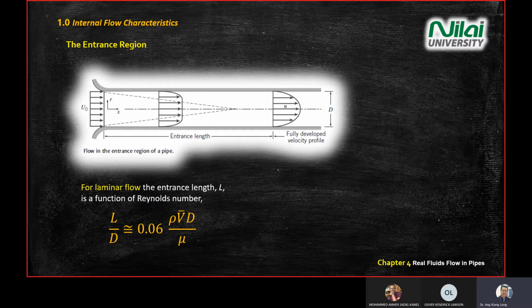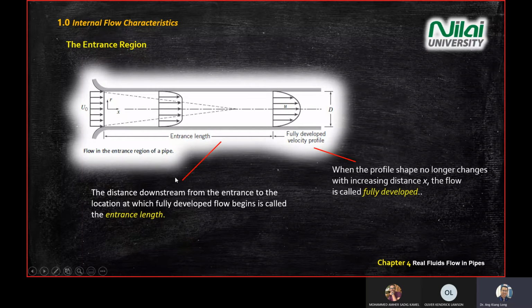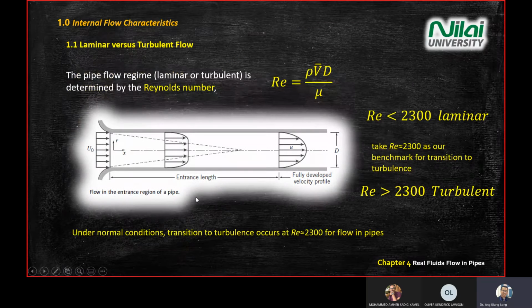So the first Reynolds number equation. Normally, the question will ask you to find velocity. After you find the average velocity in the pipe, the question will continue to ask you to define the type of flow you have inside the pipe. So the next one, you use Reynolds number and then use this magic number to explain whether it's laminar flow or turbulent flow. If the number is less than 2300, then you're having laminar flow.